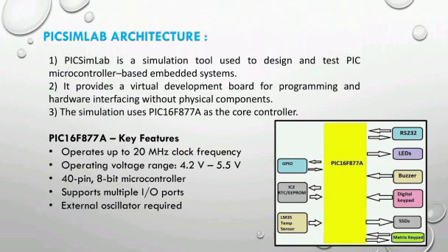PIC16F877A is an 8-bit 40-pin microcontroller supporting multiple input-output ports and external peripherals. It operates up to 20 MHz clock frequency and is widely used for prototyping embedded applications and learning.